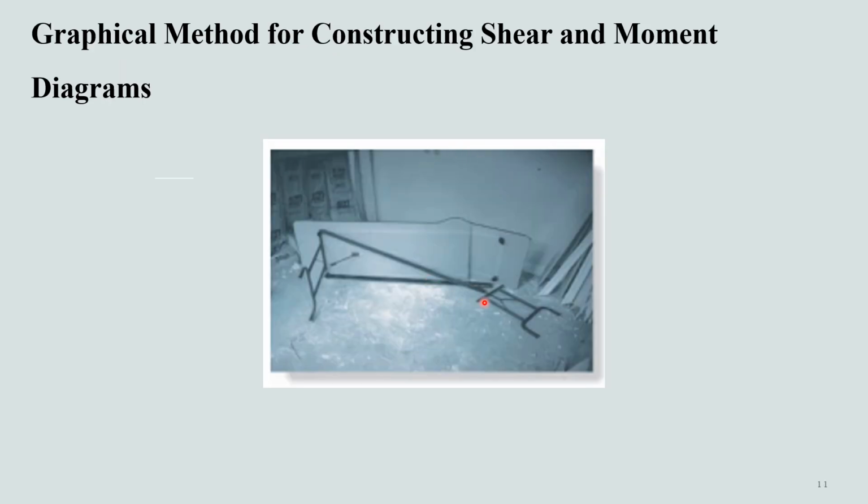Okay, before delving into more complex methods of constructing shear and moment diagrams, let's consider why we are doing this. Let's get back to this basic reason. In this diagram, you can see that the failure of this table occurred at the brace support on its right side. If drawn, the bending moment diagram for the table loading would indicate this to be the point of maximum internal moment.